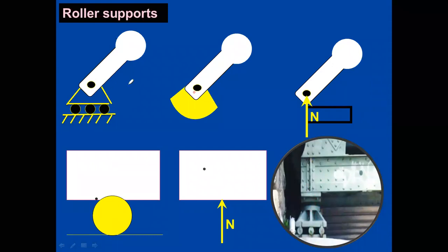Here you see the roller support has been connected to a member. This is a member, right? So it is creating some forces over the roller support, and this roller support is going to develop a reaction. Another type of roller support, a bracket example, we have given. How will the reaction develop? It will always develop perpendicular or normal to the contact surface. Against the contact surface, there will always be a normal reaction, which we can represent as R. The reaction R will develop in the support.